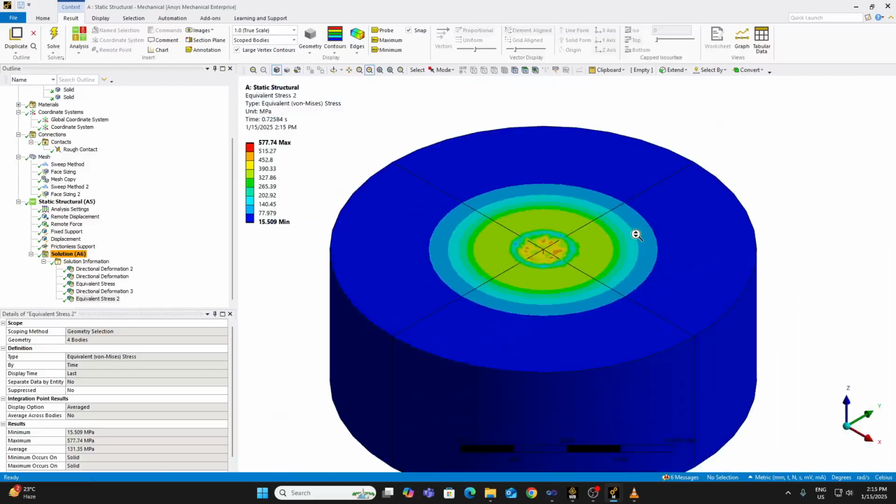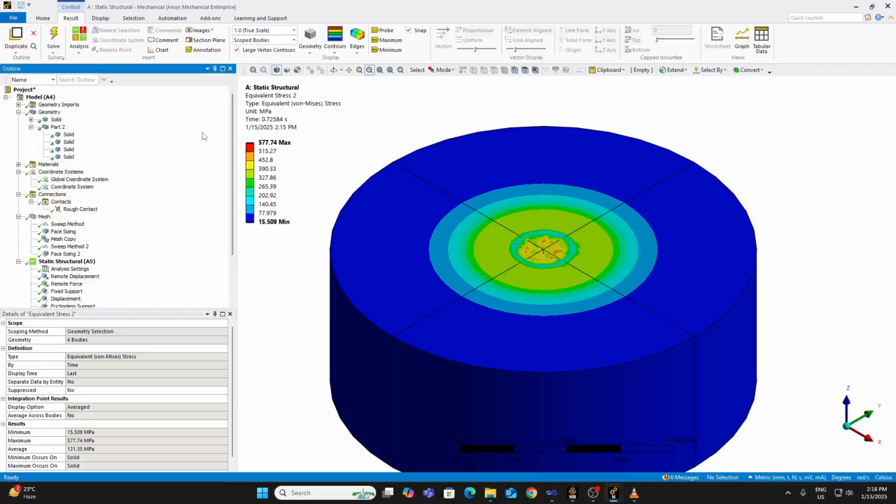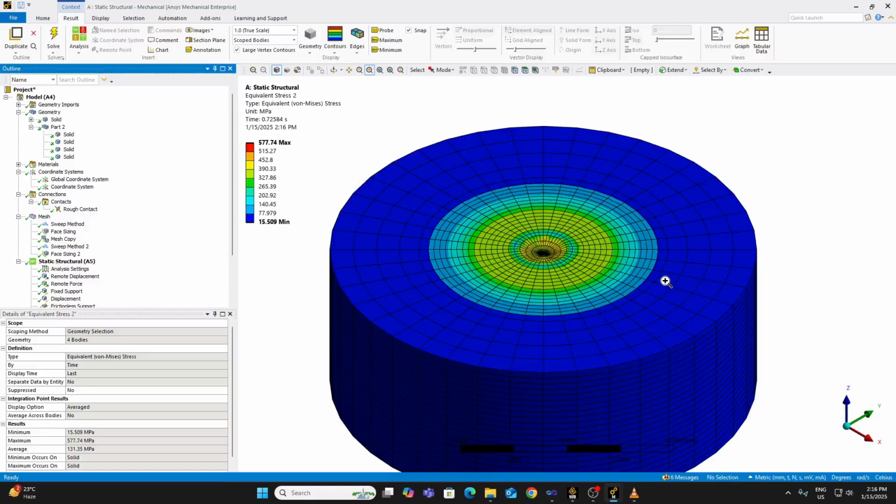Okay. So, some of the new things that we got to know here was how to create a rigid body, and then a new type of meshing was used in this particular case. Sphere of influence was used, and that is actually necessary for this particular example. Let me show you why that is necessary. Let me switch from undeformed edge to showing elements. Okay.